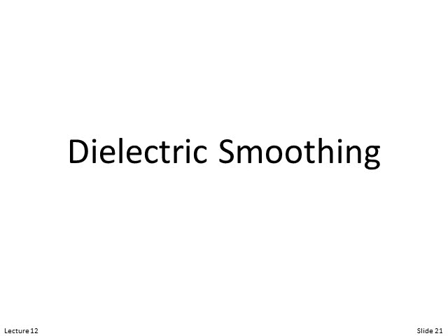Okay, on to dielectric smoothing. Here we have a device. We're going to put it on our Yee grid, which is inherently Cartesian. So we need to make even round things look like squares. And there's some implications of that. There's also some things we can do about that to improve things.